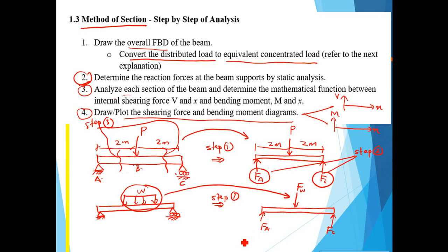Step 2, determine the reaction force, which for this case is FA and FC. Step 3, analyze each section by sectioning. Step 4, draw the shear force and bending moment diagram.